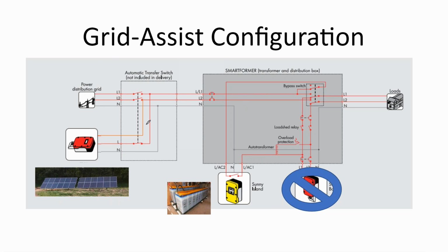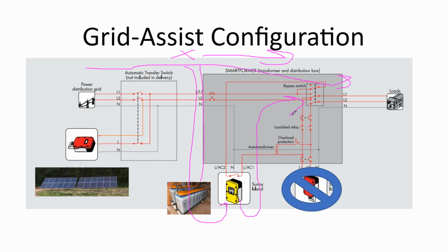But I just thought I'd mention that there are systems that are just one way, where you put a battery in between the grid and the load, and the inverter only flows into the load and not out to the grid. The grid might land on the input of the battery inverter, and the output of the battery inverter goes into the load,